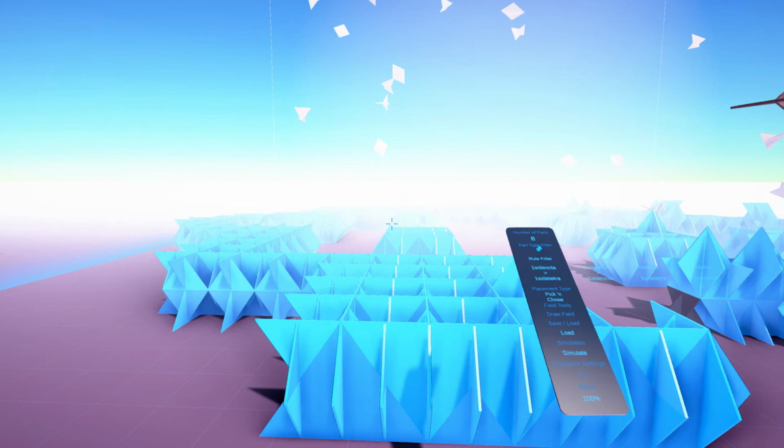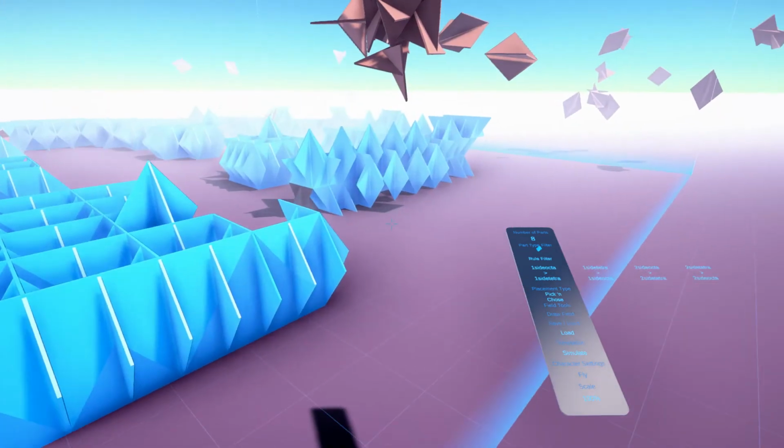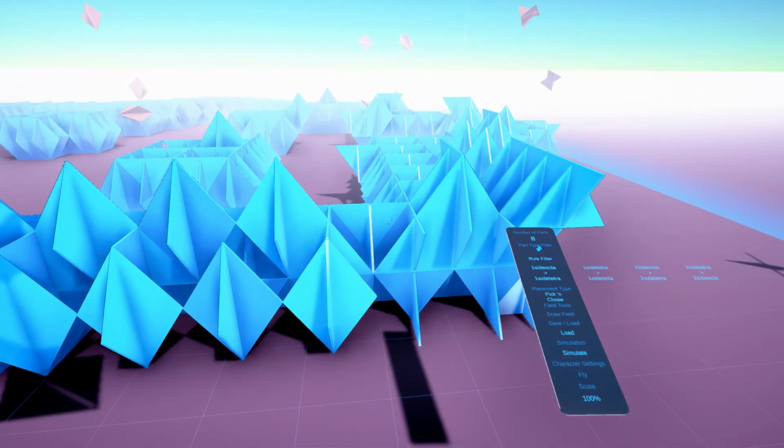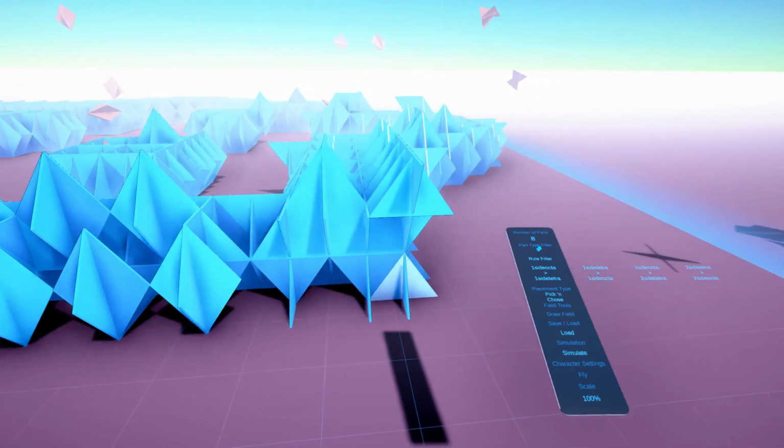But there's also the rule filters. And rule filters could be the rule grammar from Wasp, or it could be rule groups that you create in Wasp. And those again work like flags. So I could, for example, now say, okay, here we have one side octa connects to one side tetra.